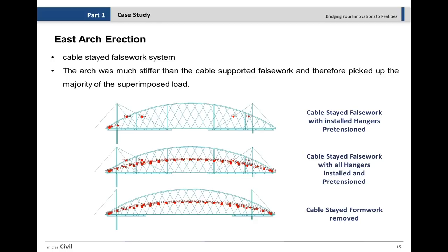Erection of the east span over the Coyote Creek pedestrian presented particular challenges. Technically, the zoo didn't let the constructor use falsework. Therefore, the constructor has to use a cable-stayed falsework to complete the erection.